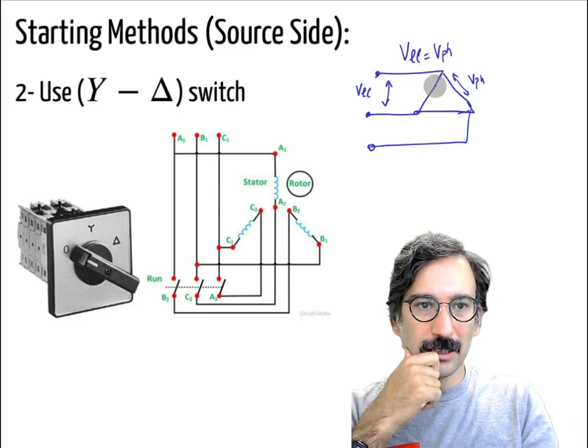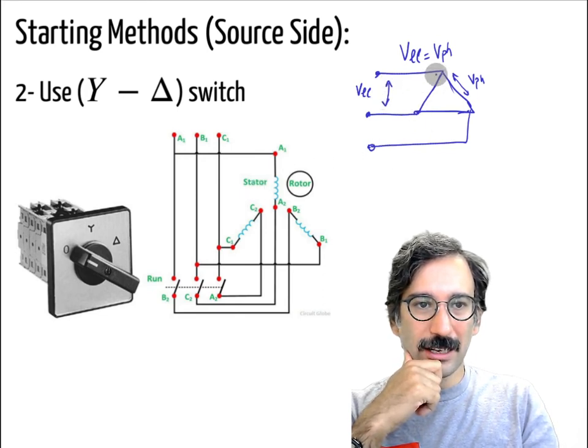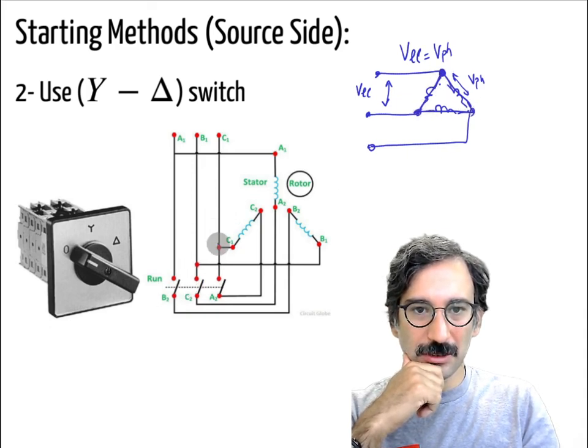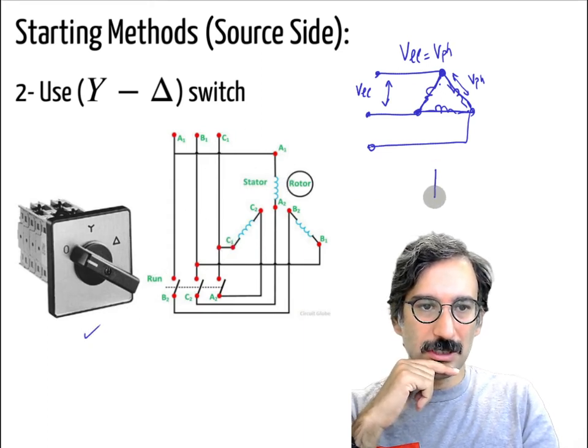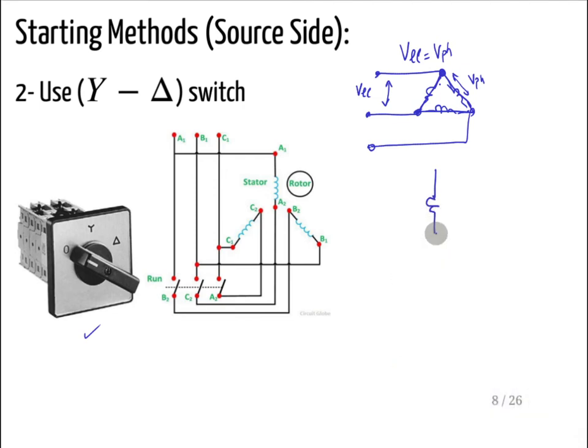But if I connect the machine in a Y arrangement, changing the per-phase circuit, you have those terminals, and I'm not going to get into detail, but you can see how they are connected by that kind of switch. With this modification, even with the same line-to-line voltage, your phase voltage will be the line-to-line voltage divided by square root 3.